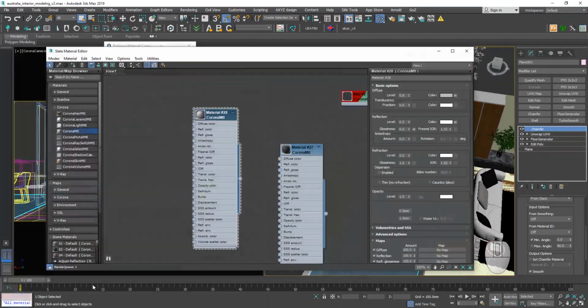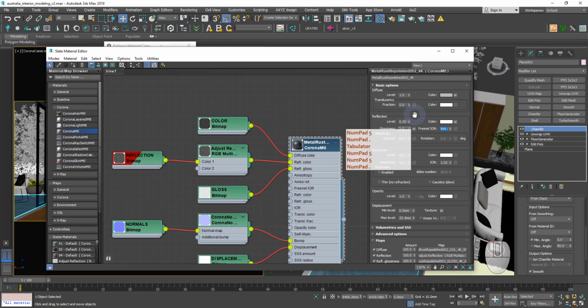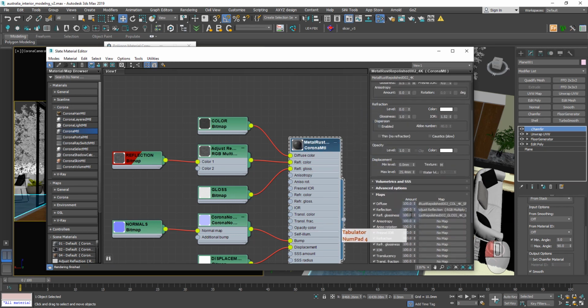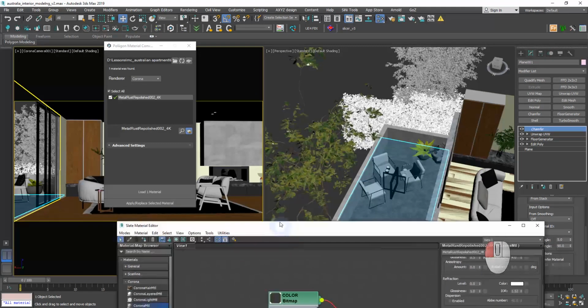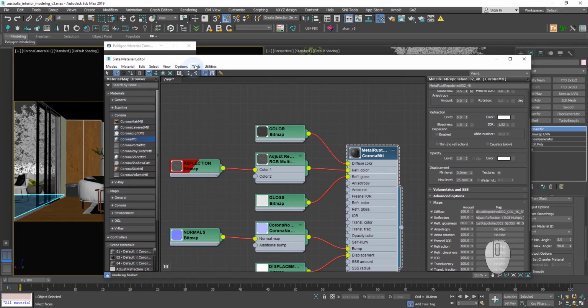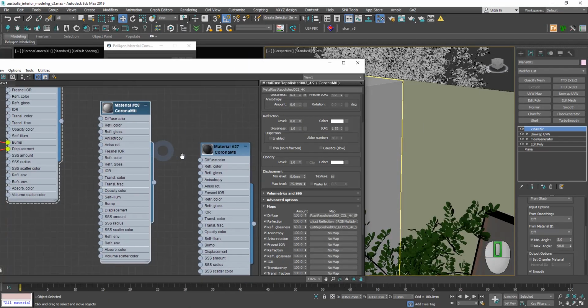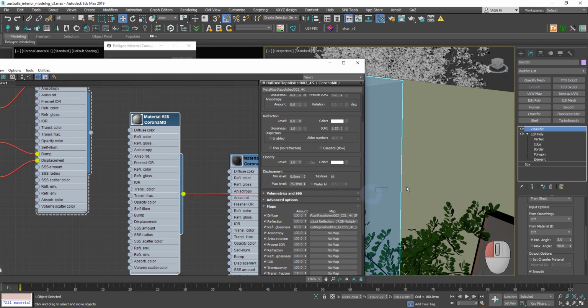Go to Material Editor. Select the eyedropper. Click on our tile. Double-click on our material and assign the parameters we need. We have only one unassigned material left, the walls. I'll take the eyedropper and use this material. It looks good for it. Just apply it on the walls.